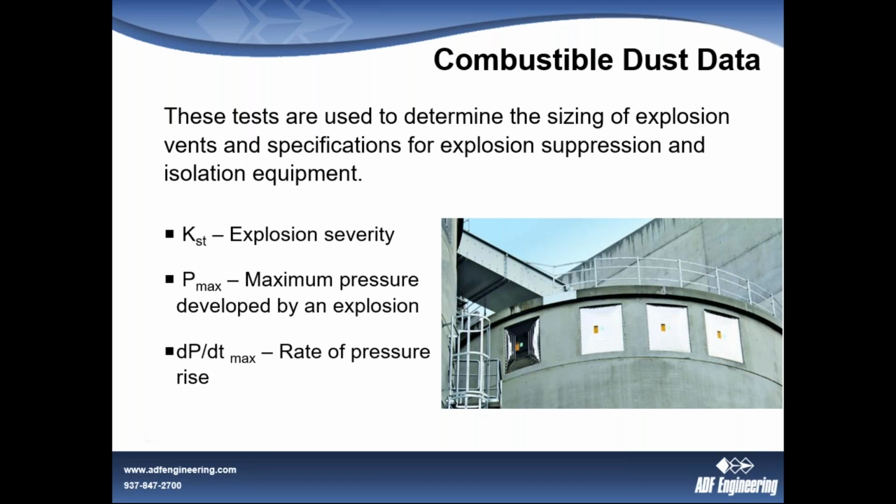You'll also get a PMAX, that's the maximum pressure rise that can be developed during an explosion. And you can, as an option, design your equipment to contain an explosion. In the grain and food industries, that's generally not done. It's just impractical to design a vessel to hold 150 psi of pressure just to contain an explosion. But if you're over in some other industries like the oil and gas industry, they do that all the time. So what works for one industry may not necessarily work for another.